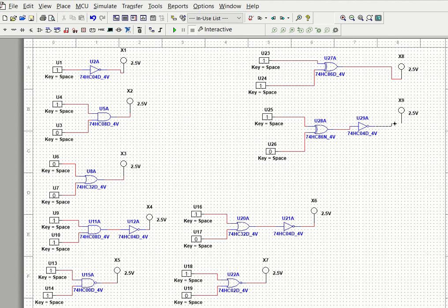Now we can hope that it might work. Let's try it out. So this is supposed to behave like an XNOR truth table, which means for 1 1 or 0 0 combination only the light is supposed to be activated. So for 0 0 it is high. Okay, it is working. 0 1 combination it is low. Let's take 1 1 combination, it is working. If you try 1 0 combination, it is not supposed to work as well, which means the output is supposed to be low.